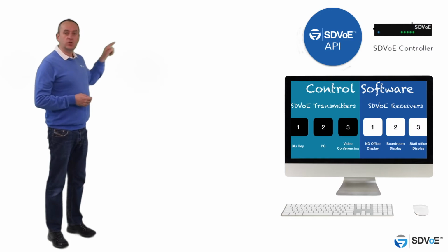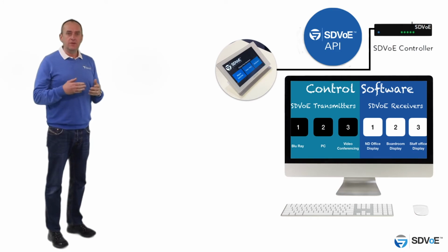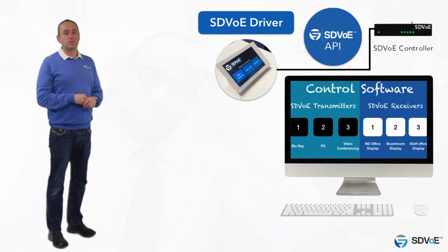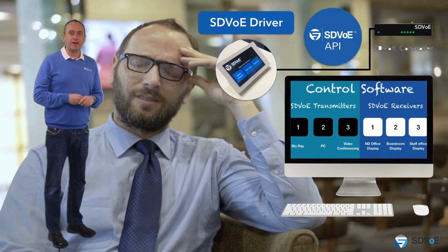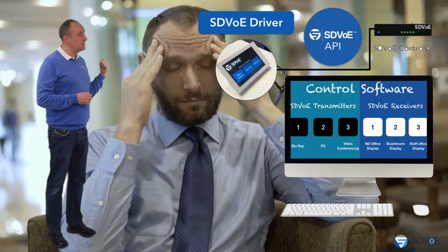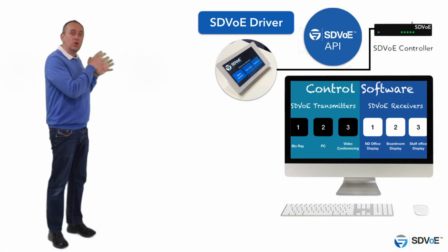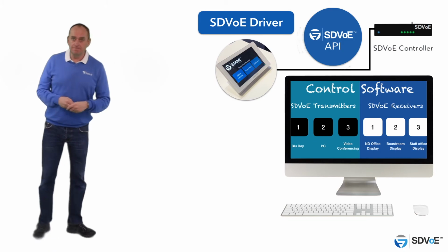SDVoE controllers can be controlled by third-party control systems in the same way hardware devices can. For any given control system, an SDVoE driver is created, and from there, integration is easy. Many manufacturers of SDVoE equipment already provide drivers for popular controllers, but make sure well in advance. Discuss this with your manufacturer before specifying your system, because you don't want to be caught at the last minute realizing that you need a new driver for your chosen control system. It's important that you budget this well into your project well ahead of time if what you need doesn't already exist.